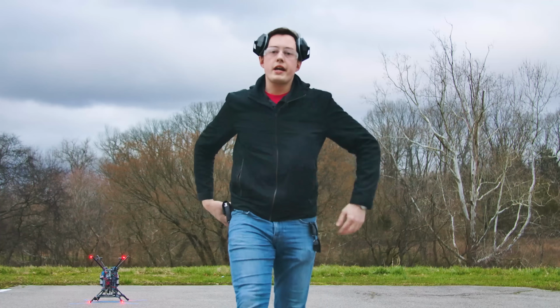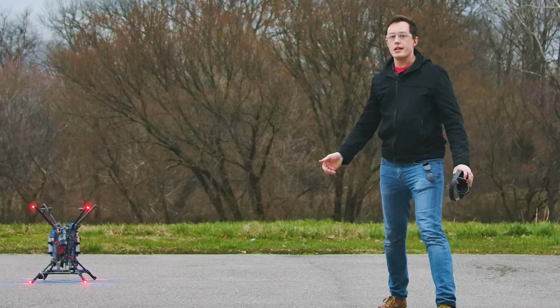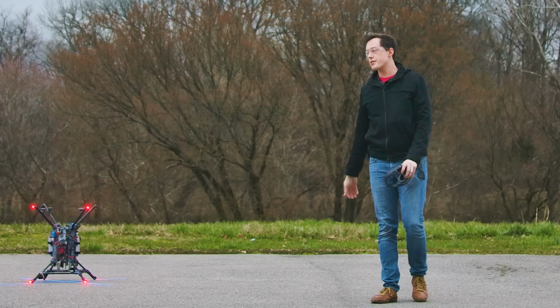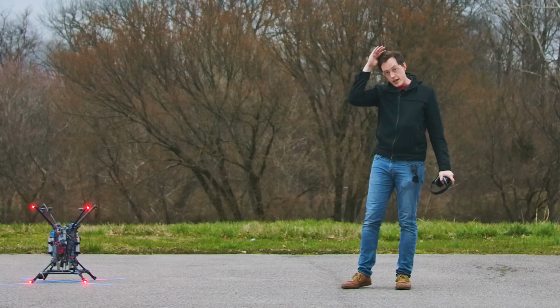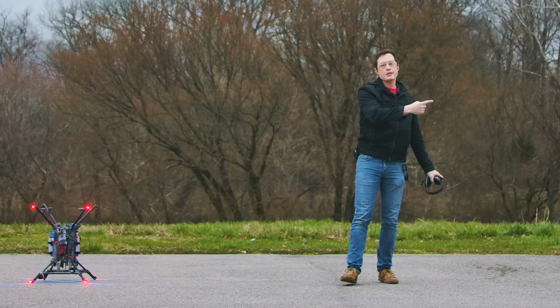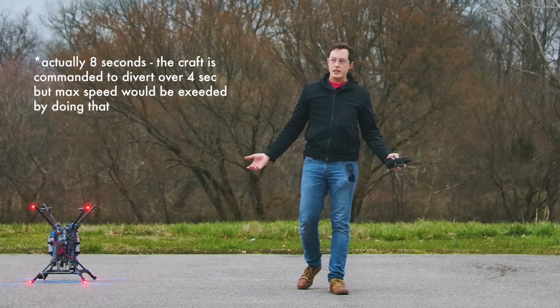Let's do more. Okay, this is a 4 meter divert on the y-axis, and it's happening at 2 meters above the ground. So the craft is gonna ascend to 2 meters, hang there for 2 seconds, divert 4 meters on the y-axis over the course of 4 seconds, and then it's gonna come back down to the ground.